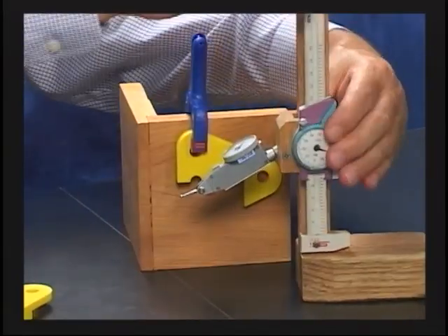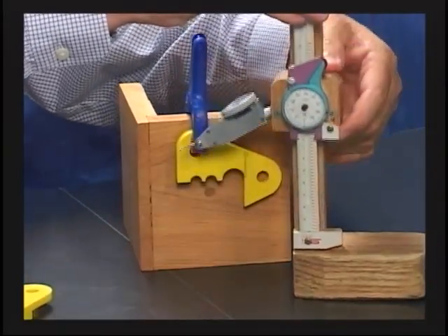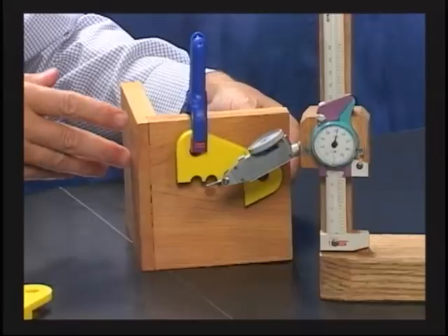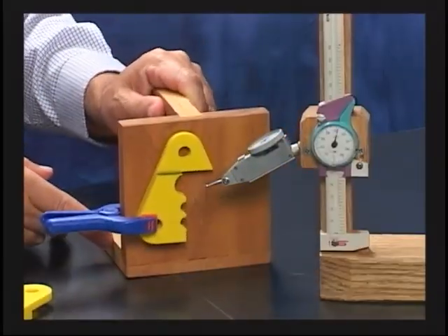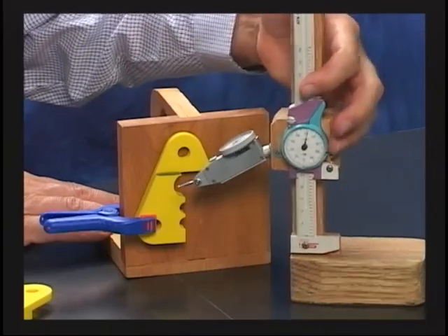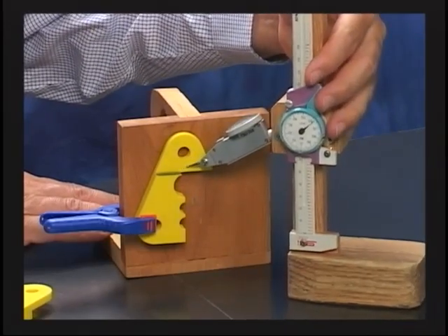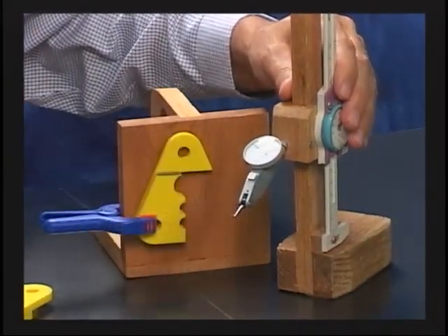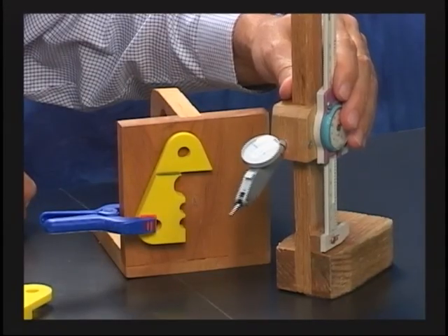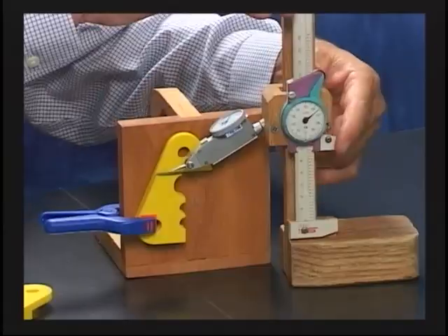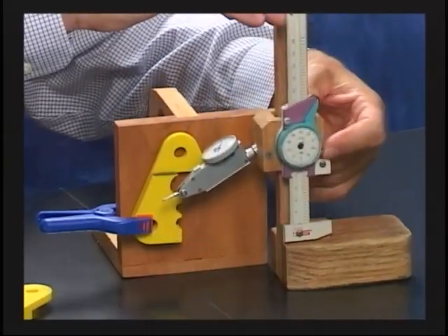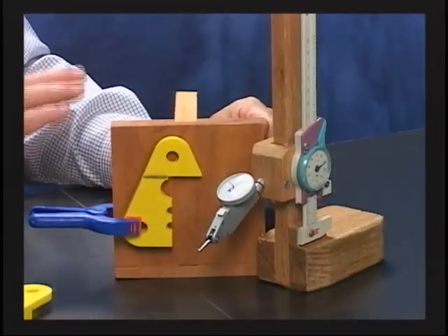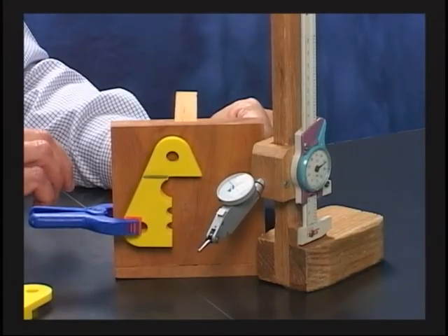Once I got that, I can make any measurements that I need to in this direction, right? I could go in and measure where the hole was. I could come in and measure points across here. Now, if I wanted to measure in any other direction, all I do is move 90 degrees. When I move 90 degrees, I'll come in and get a 0 on this face over here. Remember, that was my datum in this direction. And when I run my needle across here, do you notice that needle couldn't move any more than 5 thousandths. That was my perpendicularity. And then from there, I can make any measurements I need to in this direction to center the hole and do my positions in this direction. So you notice how important it is to have a datum reference frame. If you have a datum reference frame, everybody sets the part up and measures it exactly the same way.